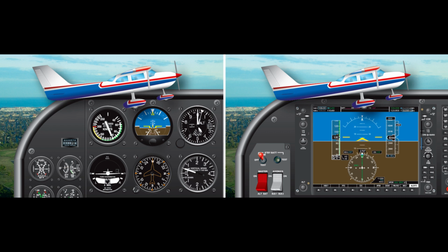Common errors in the performance of climbs and climbing turns are: 1. Attempting to establish climb pitch attitude by primarily referencing the airspeed indicator and chasing the airspeed. 2. Applying elevator pressure too aggressively, resulting in an excessive climb angle. 3. Inadequate or inappropriate rudder pressure during climbing turns. 4. Allowing the airplane to yaw during climbs, usually due to inadequate right rudder pressure.